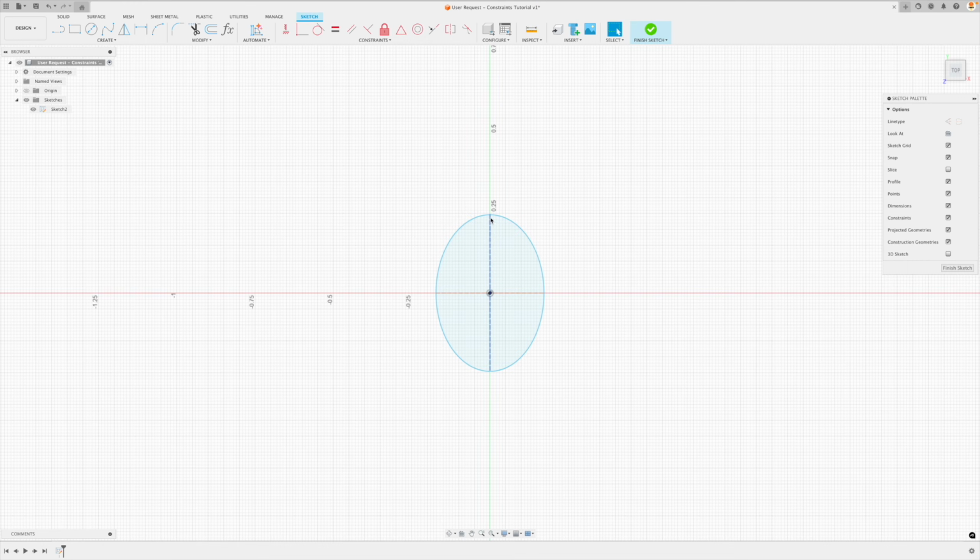So this is great. Now let's move it. Now look at what we've got. We've got this part wandering all over the place. So we can try and constrain this line, either vertical or this line horizontal, in order to lock our part right down. Now, we could just click on our line, and it turns vertical.